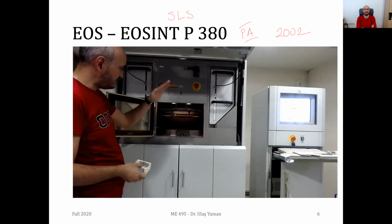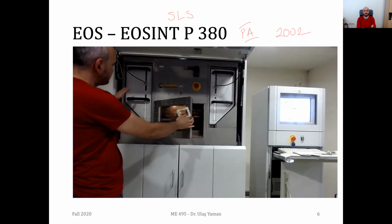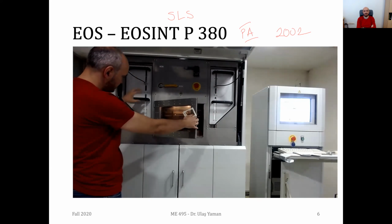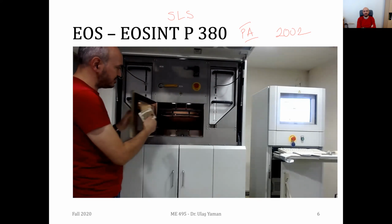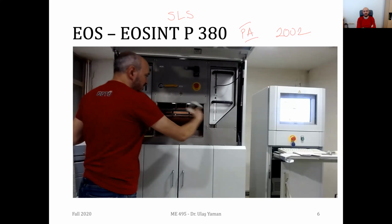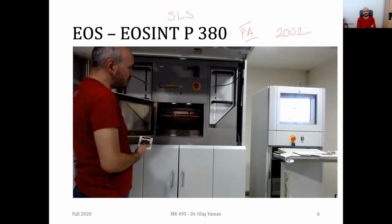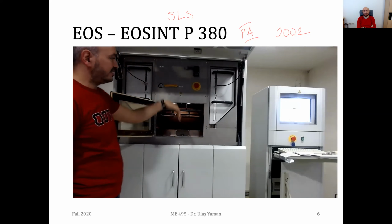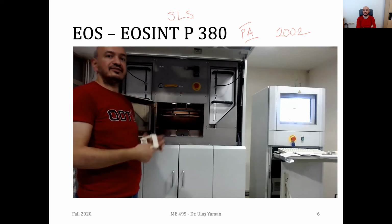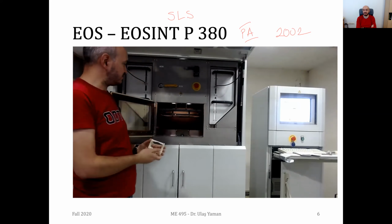And then if that layer is completed, another amount of powder is poured once again into the carriage. And this time, the carriage moves from right to left. Another layer of powder is spread, and then the laser simply again sinters the powders, and this goes on until your part is completed.